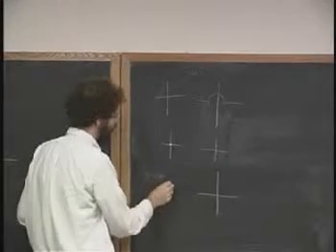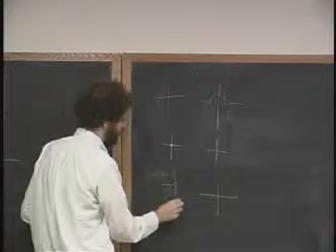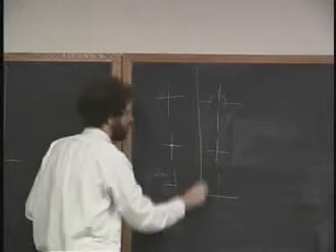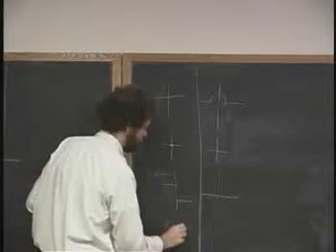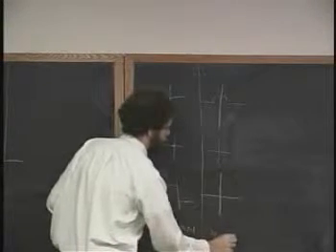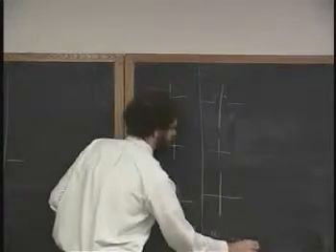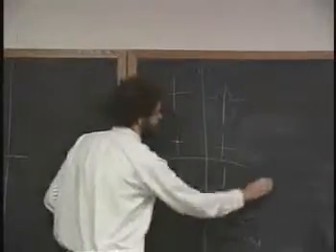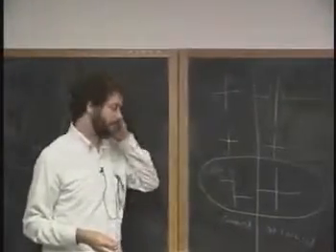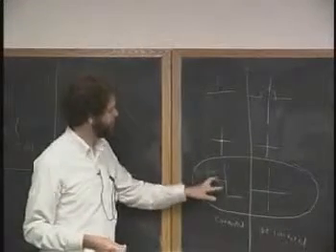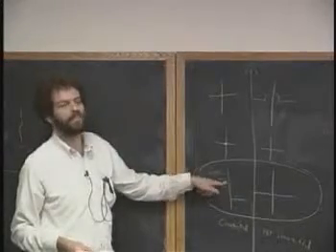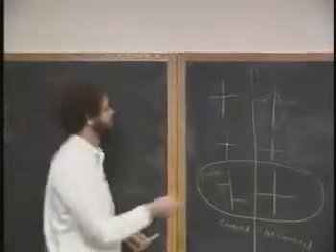So the new way of doing it, since the 1970s, is that these are wires that are hooked up, and these are wires that are not hooked up. So I'll put this as connected, and these are not connected. And of all these methods, this is the only one you should ever use. Okay? So any things that meet at a point, they are hooked up. And if you want 4 wires, then you have to do this. And 3 wires, it's clear that they must be hooked up, because why else would you do that, right? So just a bit of draftsmanship here.